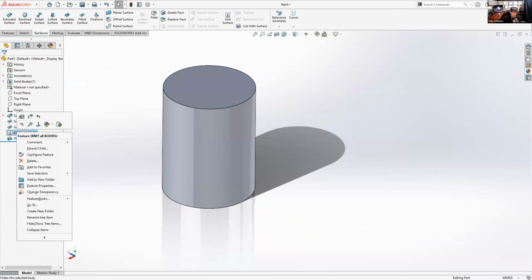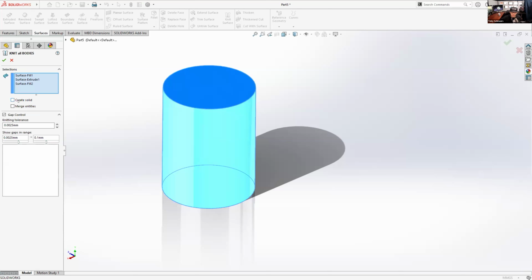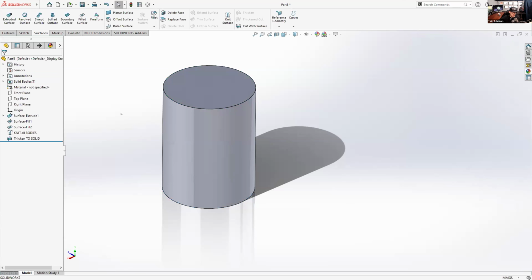So then the question is, well, why didn't you just do create solid here? That does the same thing, right? Well, the answer is because a lot of times in surface modeling, you knit surfaces to facilitate a complex trim, but not every time you knit are you necessarily turning it into a solid. And so I didn't want there to be ambiguity when I would look back at the feature tree and wonder to myself, wait, is that the one where I knit it and solidified it? Or is that the one? So instead, I just make it a rule. I just always do it as 2 features, even though you could do it as one. This makes it a lot easier for me to look at the tree in a year, when that customer asks me to move that surface over a little bit, and understand what's going on with that tree.